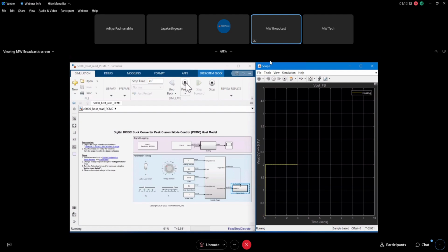One thing to note here is that the ramp we have calculated for the comparator's reference slope is with respect to the reference voltage of 2 volts. So the ramp will continue to work in a small range in and around 2 volts. But if you try to move beyond that range, probably more than 4 volts or less than 1 volt, the system behavior may not be as expected. You may have to recalculate the ramp with respect to that reference voltage.